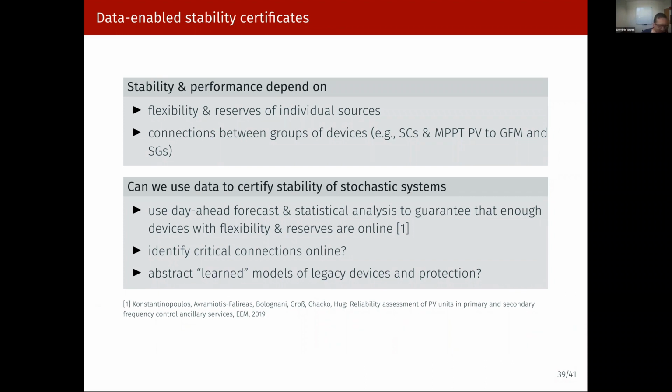There are some results that would allow, as long as you know the network topology, you could go with the completely unstructured model of, say, the transfer function between the power injection into the grid and the voltage angle that the converter is putting on the network, but we have not really explored those.